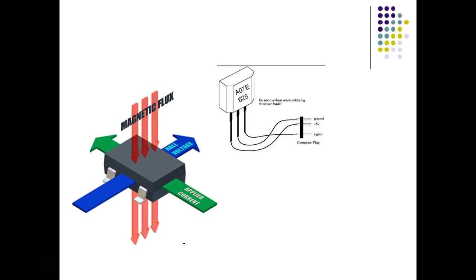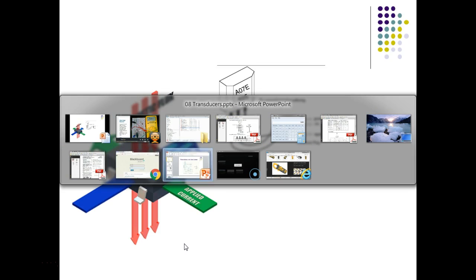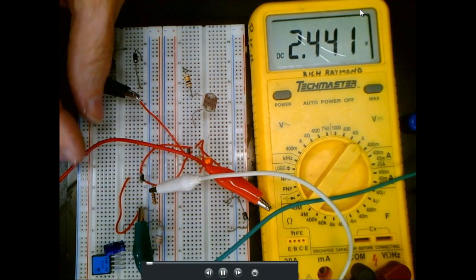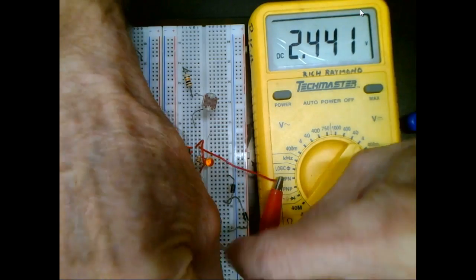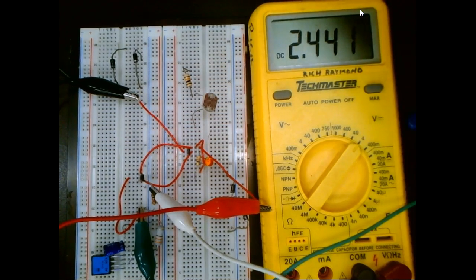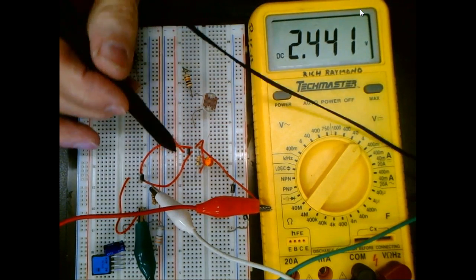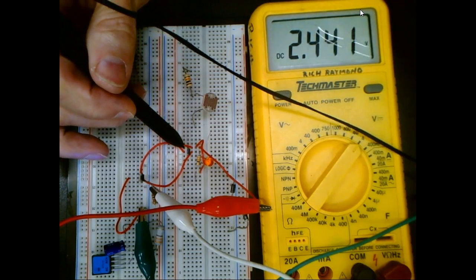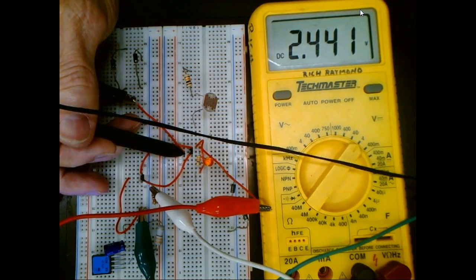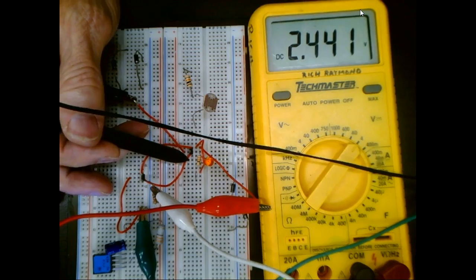Okay, I hooked up the linear sense Hall effect. It's a sourcing sensor. So here's my circuit. I'm sorry I got all the same color wires, guys, but power comes in on pin 1, should be right here. This goes up to 6 something volts. If I'm using 5 volts, that's okay. Pin number 2 is my common, and then pin 3 is my output.